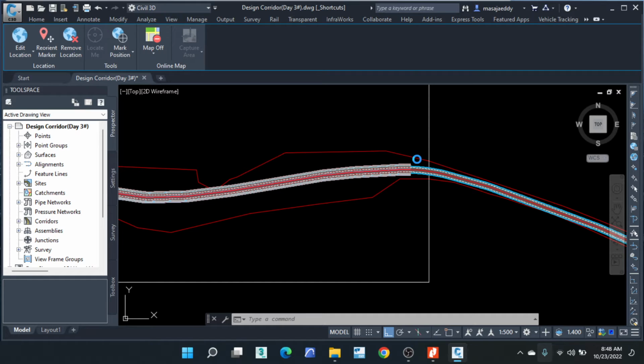What we are going to do, remember we reduced our frequency to a lower figure. That means that there are a lot of polygons within the drawing, which makes it very heavy. So if you're able to access it, you can increase the frequency to the normal frequency, which is 20, so that we reduce how many polygons you're working with in the drawing.